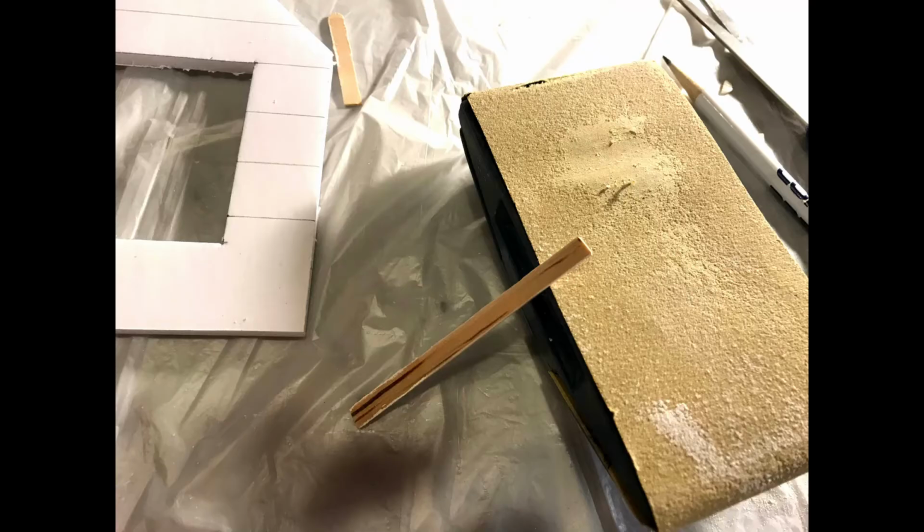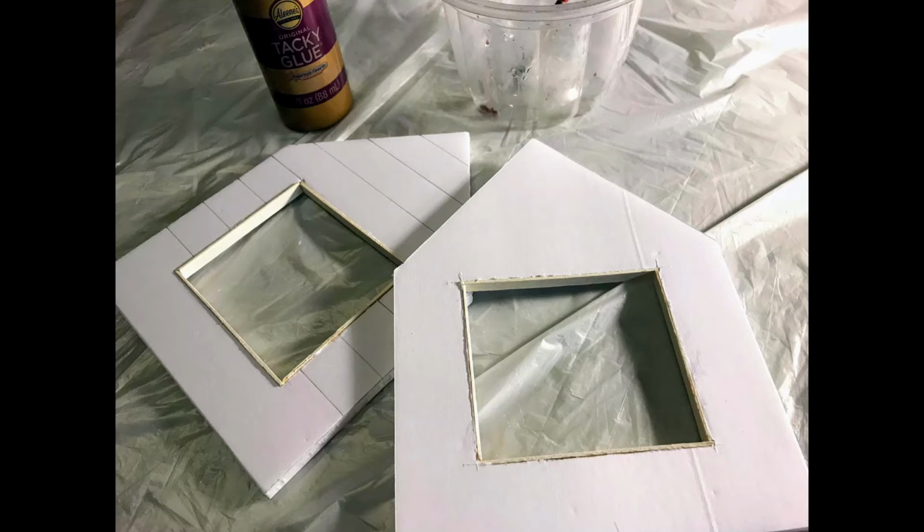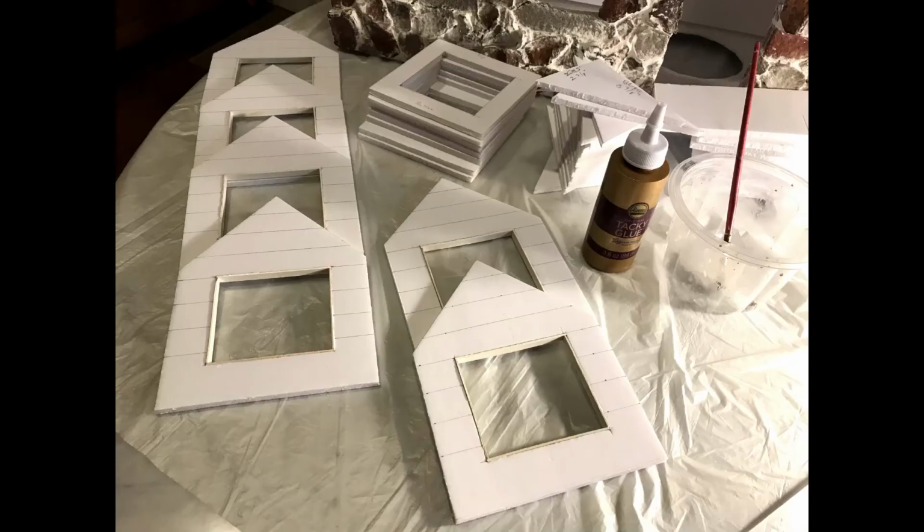I lightly sanded the edges, then allowed the tension to hold the trim until I was ready to glue. I tried to keep the edge of the trim flush to the back side of the dormer and have the extension raised above the surface on the front side. It will work better to have a completely flush surface on the back for the window to be mounted. Also, when the shingles are applied to the front, this provides a finished frame to butt up to the shingles.